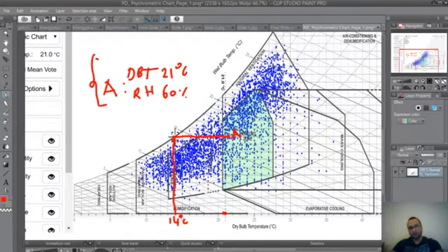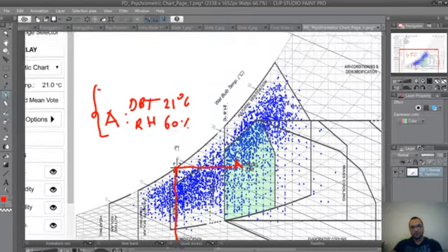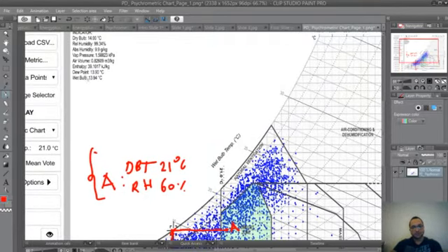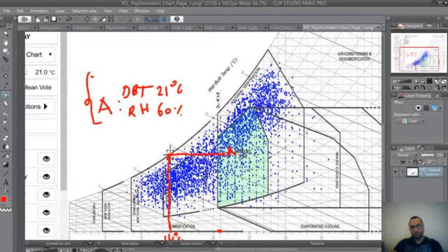Okay, the values that I have figured out using the graph are also automatically displayed by the tool. So I have the dew point temperature around 14 degrees Celsius. However, we have to know how to use the chart and to figure out the different temperature, whether wet bulb or dew point temperature. And this is very important.